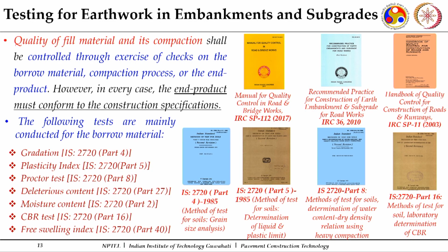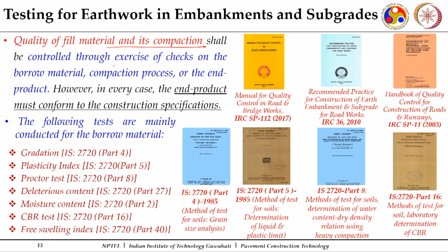Now, this is one part of the check, where we are checking the surface levels and the surface irregularities. Then come the checks related to the material part. So, the quality of fill material, what quality of material we are filling and how we are compacting it, those checks are also involved. It shall be controlled through exercise of checks on the borrow material.